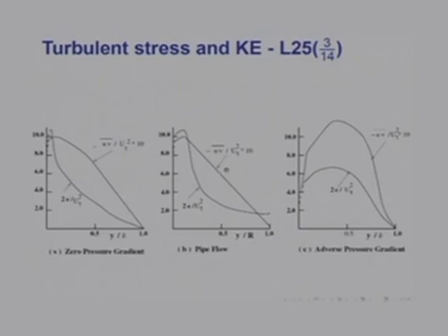But frankly speaking, the shear stress is the total stress, and in this part the laminar stress of course would be very negligible. But as you go close to the wall, the turbulent stress drops down, but the laminar stress would begin to dominate. Therefore, in the inner part of the layer, the constant stress layer assumption is not a bad one.